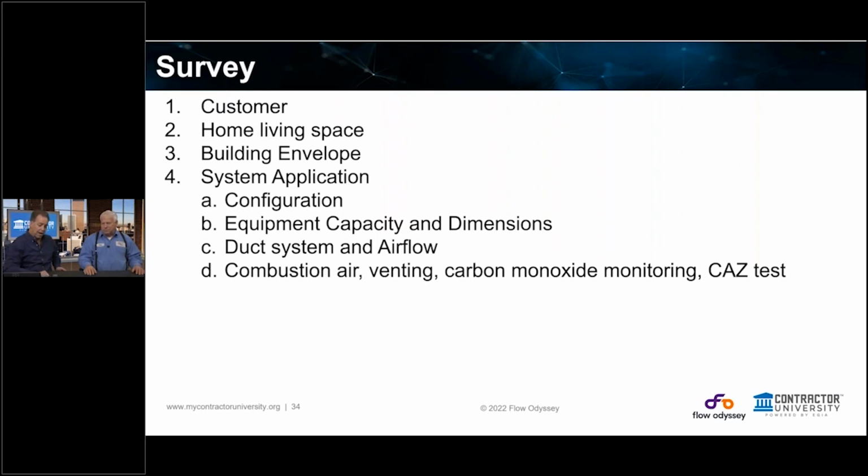Yeah. I know you wanted to talk about this when we built this class. So we go into a house. It has a heating and air conditioning system, right? Gas furnace, propane furnace, oil furnace, or a boiler, because this is where this particular issue happens. And so we've got to verify that we have adequate combustion air. Combustion air is air that allows the fuel to burn, right? And just because you inherit a situation and it's operated all this time doesn't mean, number one, that it's safe and up to code. You have to verify this.